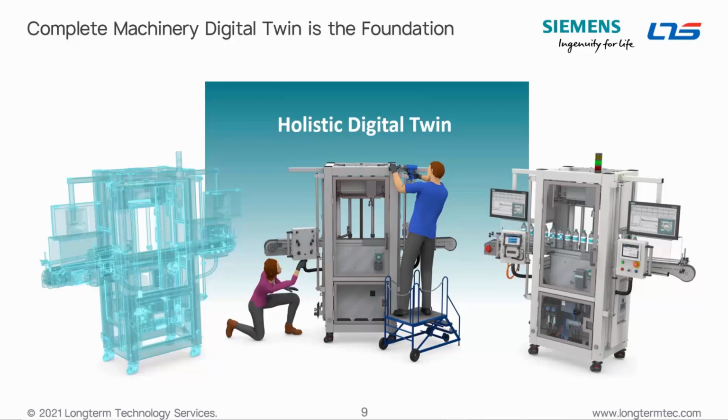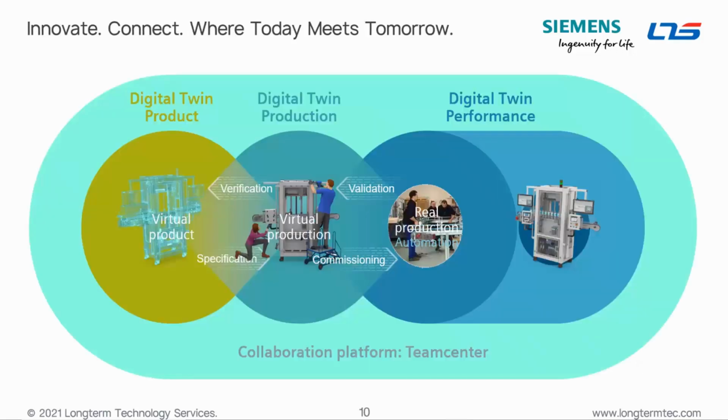So let's say you're talking about a digital twin of a pick-and-place robot, right? If you speed that robot up too much, eventually the laws of physics are going to kick in and make that not feasible, but as you keep speeding it up. But just as important for this webinar really is bringing in that automation component as well, because these simulations can run from real PLC code, right, and be driven by real controllers. So you can generate and validate your PLC code from the same model that your mechanical and electrical engineers are using to validate their own designs.